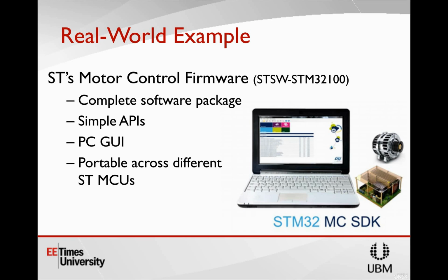But what tends to be most common is having two phase current sensors and doing the reconstruction on the third. Obviously, for applications that require much higher dynamic performance, they have all three phase current sensors. But there are also algorithms out there that can even use just a single sense resistor, and that's a much more advanced algorithm for doing this kind of FOC and sensorless control. What we talked about today scratches the surface, but there are other advanced algorithms out there designed to help remove the reliance on some of those hardware pieces.